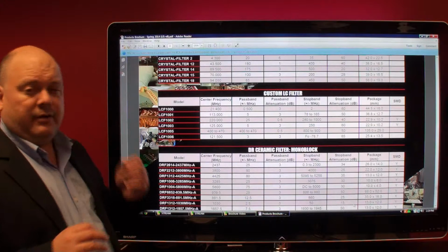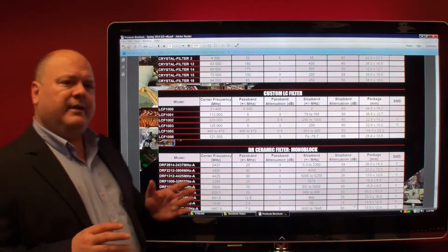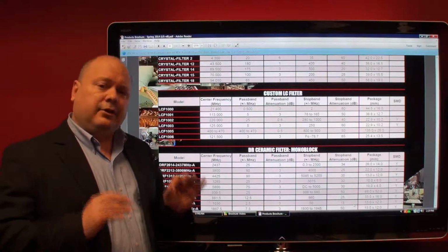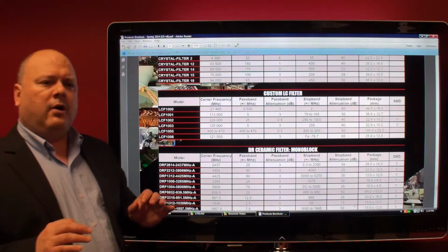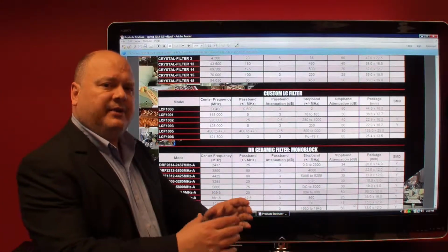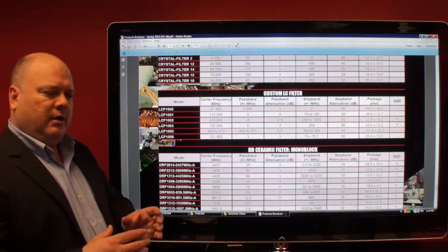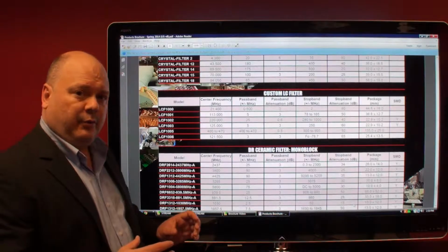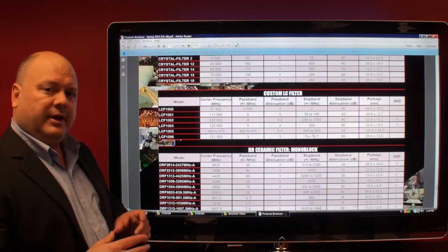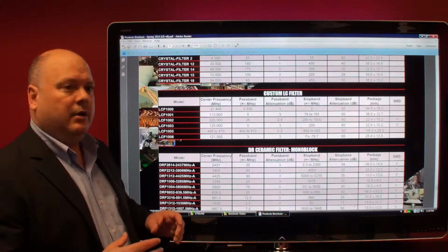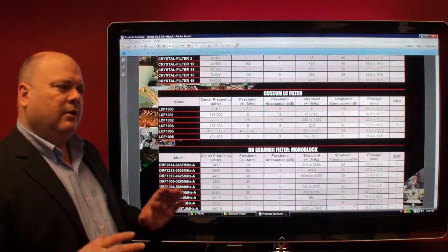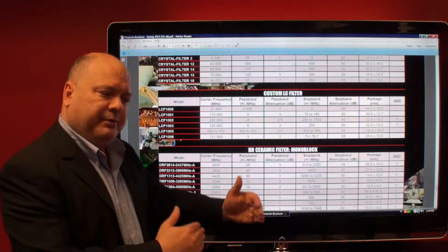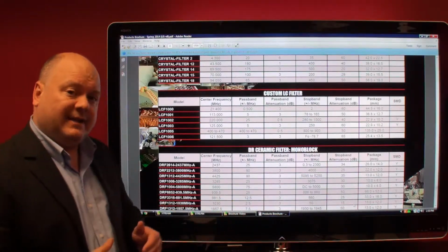In addition, like the crystal filters, we have an LC filter bank capability. What I mean by that is either tunable LC filters or individual LC filter subsections in which a PIN diode switch network is used to software switch between the different LC filter subsections for frequency hopping radio, software defined radio. Again, we have already established designs of LC filter banks, multiple sections, maybe 6 sections, maybe 8 sections.